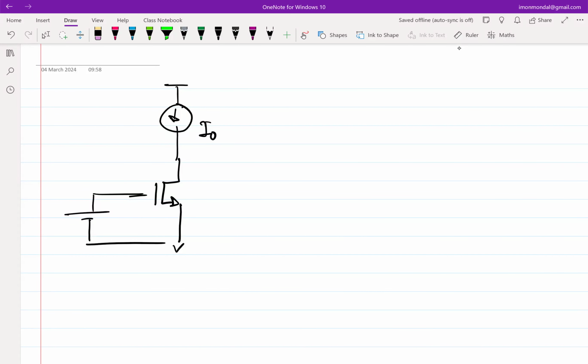And the issue that we found with this was that now there are essentially two independent sources, or rather two independent variables, in the circuit. One is this voltage source, which is asking the transistor to, let's say this is VGSQ, bias itself at a current of IDSQ.